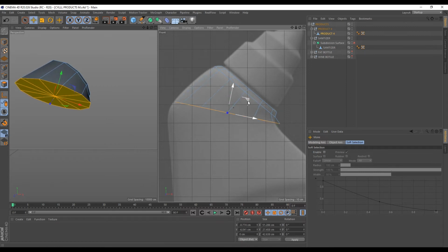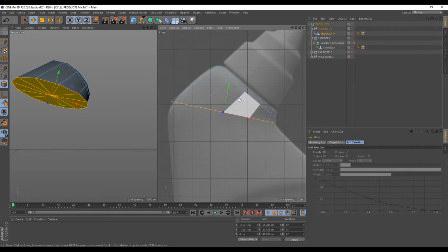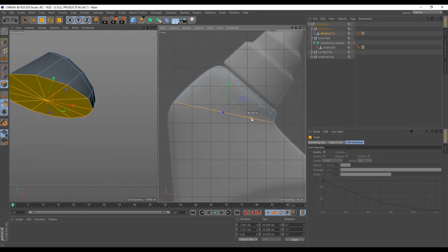Then I'll use E to move this way. So I can also use this blue icon to move my object freely in this 2D space. So what that does is that it isolates only the z-axis, and as you see, once I put it here, it selects only the y and the x-axis. So let's shape this into position. So I'll hit T, and then I'll just start shaping this.